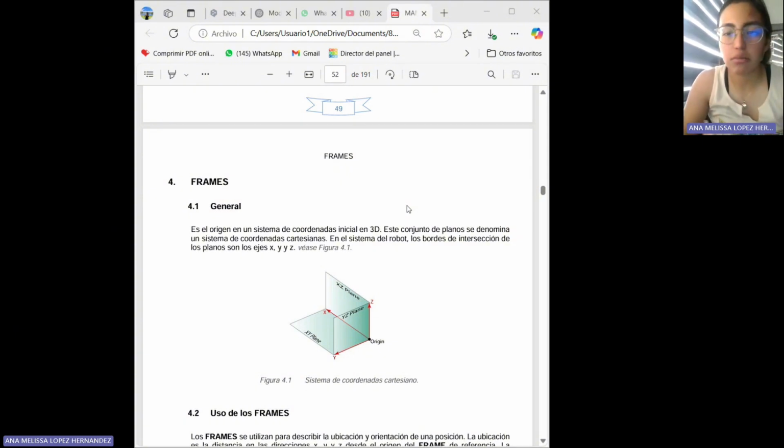In this practice, I will talk about the reference system that is set directly on the tool used by the robot. Its main function is to allow the robot to perform precision movements, always considering the position and orientation of the tool. When the tool is changed, the tool frame must also be adjusted to ensure that the robot continues to operate accurately and efficiently.